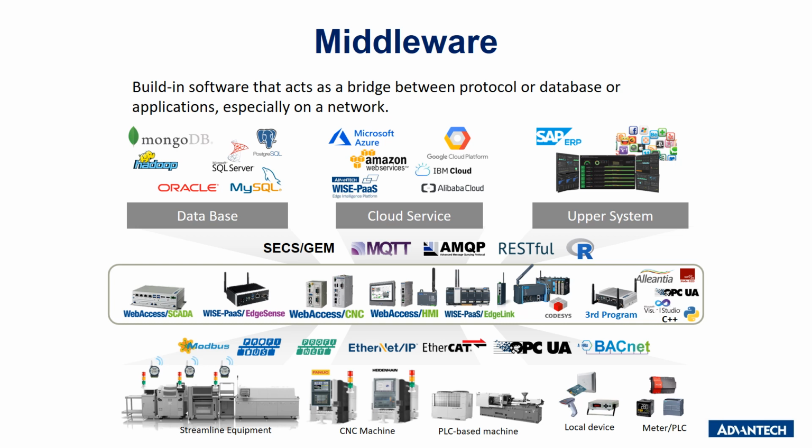It supports converting field site machine data with different protocols to another site and protocol, to link data to a database, cloud service, or another upper system. There are some ready software tools that can help to do the configuration, and users also can develop their application by using PC-based languages. Some new generation controllers have already built in the middleware function without adding an additional gateway.